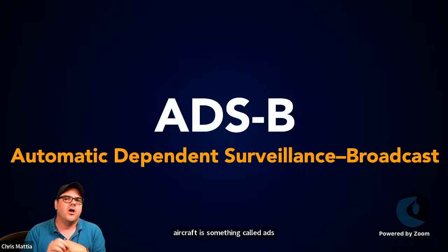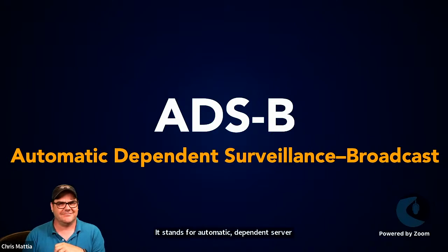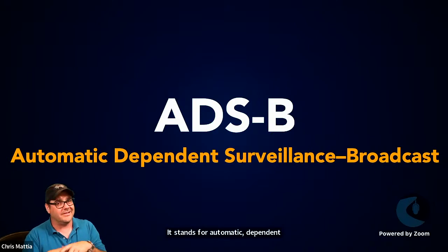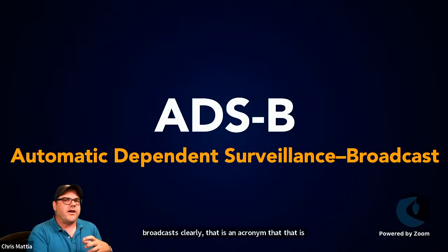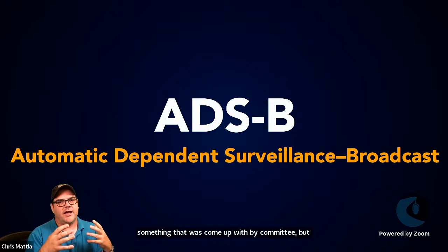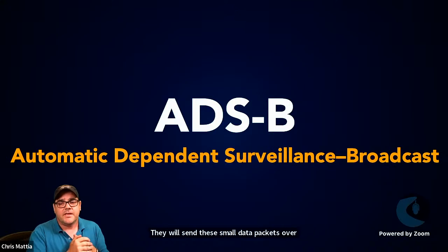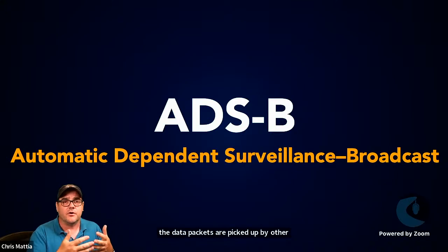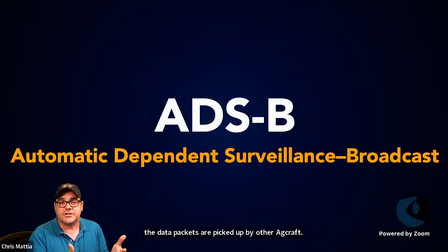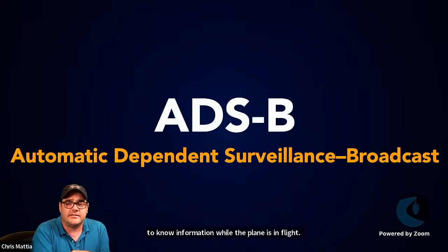It stands for Automatic Dependent Surveillance Broadcast. Clearly, that is an acronym that was come up with by committee, but essentially, aircraft that are all flying around will send these small data packets over the air, and the data packets are picked up by other aircraft. They're picked up by the towers and so forth in order to know information while the plane is in flight, and they're constantly beaconing this information.